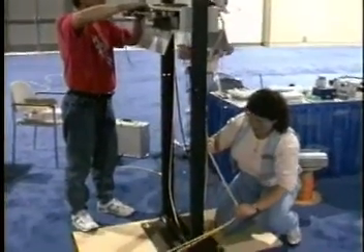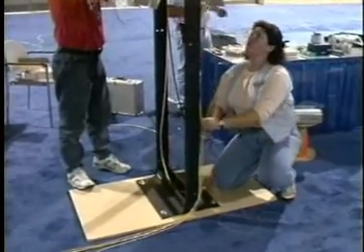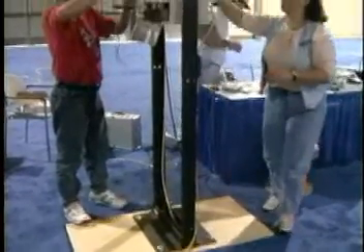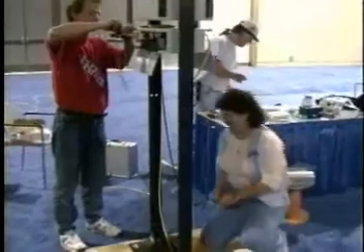Horizontal cable is routed from cross-connect panels to individual users. This can be done through plenums or by the use of undercarpet fiber optic cable. Horizontal cabling can also connect the riser section with the building entrance facility. Entrance facilities are required by electrical codes as a transition from indoor rated cable to the outdoor styles used in inter-building applications.